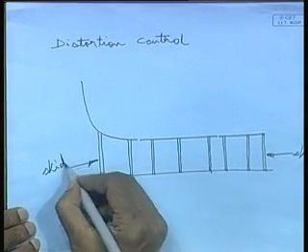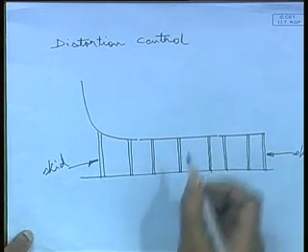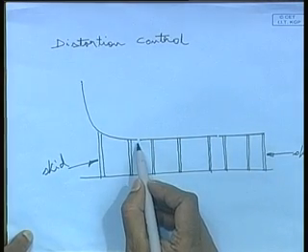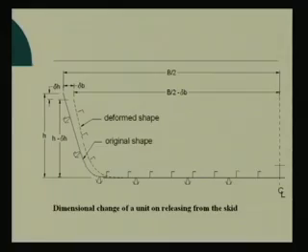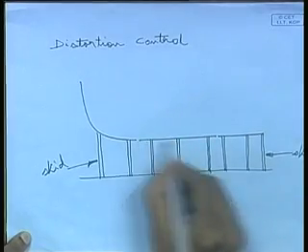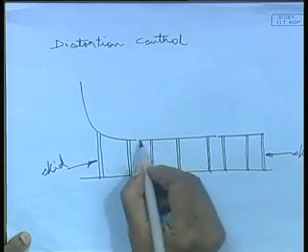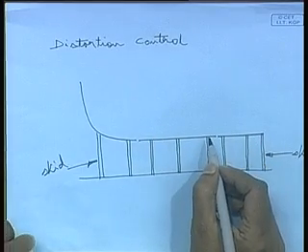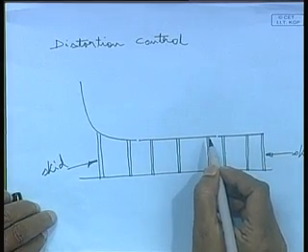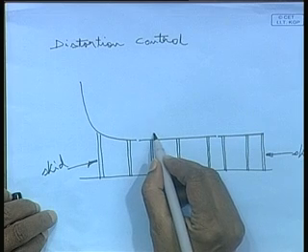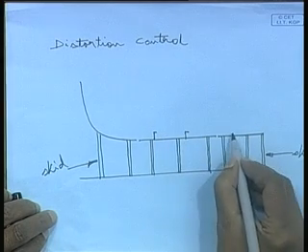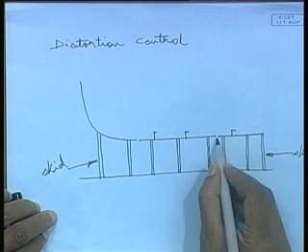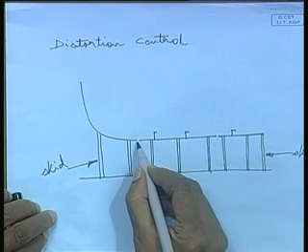Skid, right. Now, as you can see here, I have given a small gap. It is nothing but to signify the root gap between these two panels. Here I have shown the plates; it can be just flat plates or it can be prefabricated stiffened panels also. That means you already have the longitudinals welded over it, whatever is the case. So, these are the gaps, root gaps.